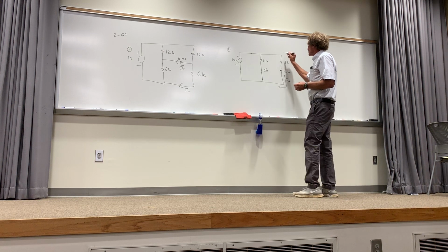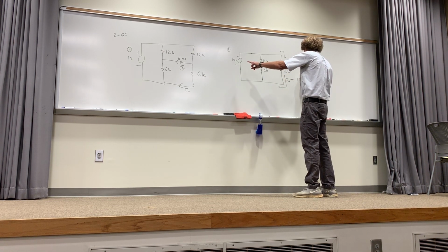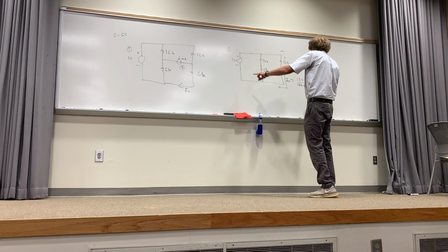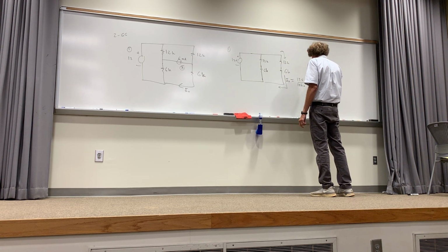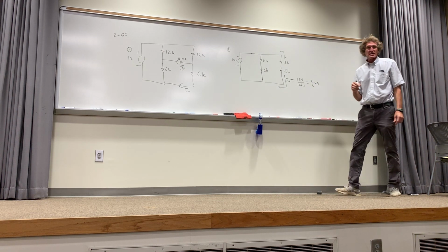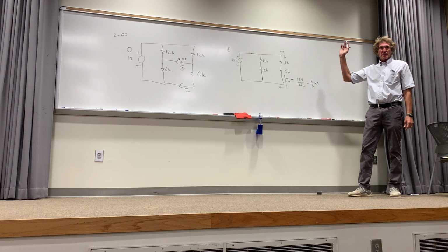The current through this one, therefore, that current I0, will be 12 volts divided by the series resistance of 18 K ohms, or 12 over 18, right? Or 2/3 of a milliamp. You could put 0.666 milliamps. Do you agree with me, class? Show of hands, how many see that? It's that straightforward, that's the first part.